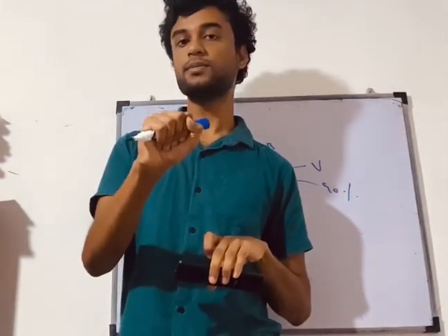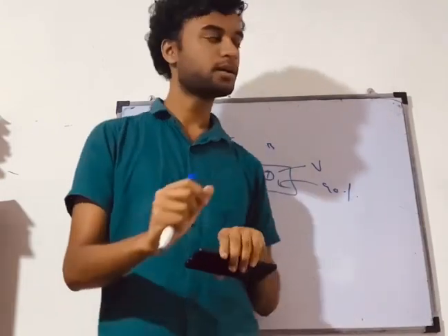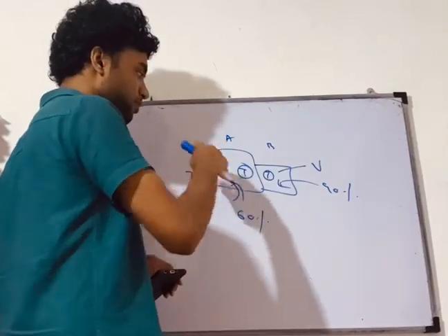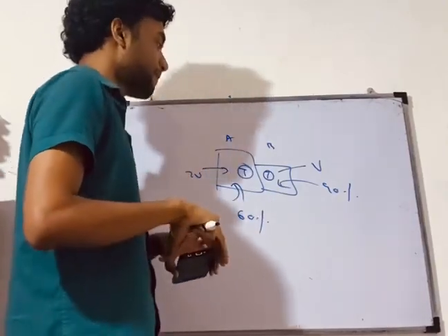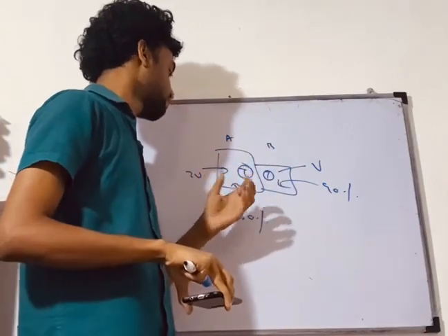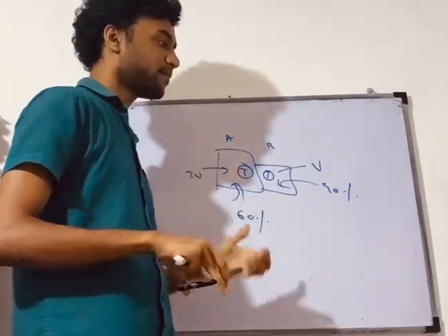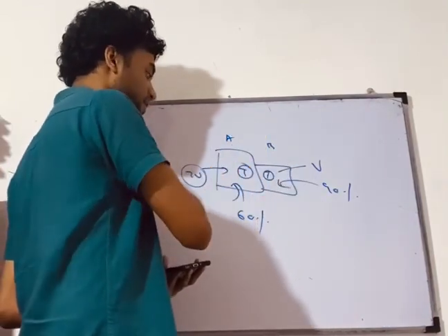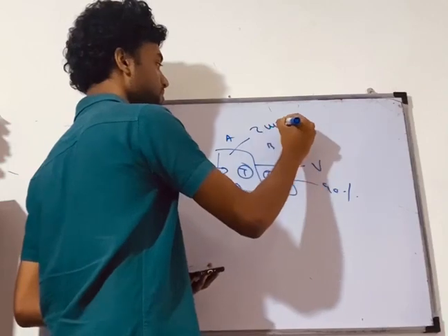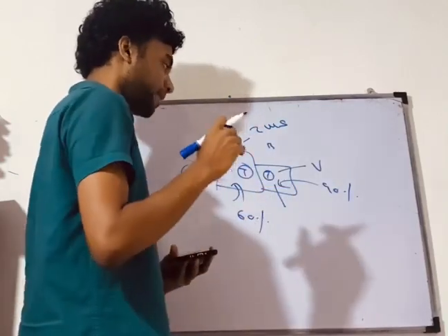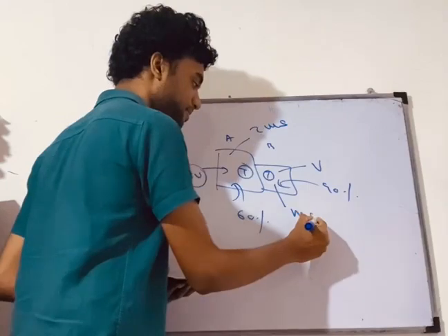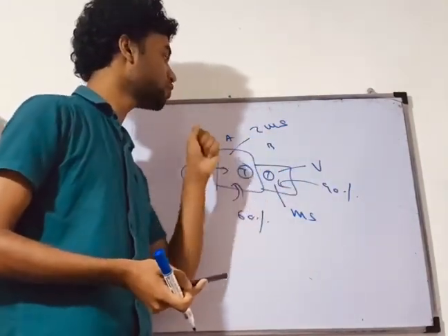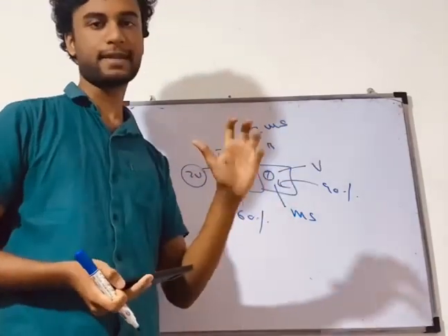But the mass per unit volume is going to be the same. Is that clear? So if the mass per unit volume is the same, what can you say the mass is for saturated state at A? When you consider a room A which is saturated, which has a volume of 2V, I can say the mass is going to be 2 ms. And the mass at saturation in room B should be ms, because the volume here is V and the volume here is 2V. So there should be twice this to saturate room A at the same temperature.